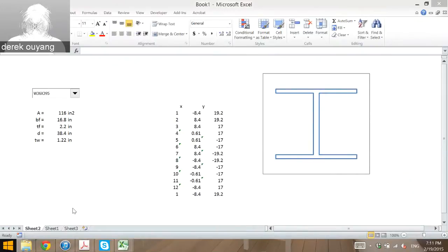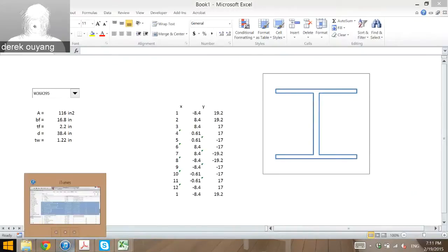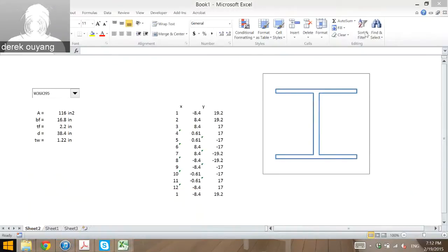That's not part of the assignments, but the thinking there is that if you're in some design process and you had a range, you just wanted to see the available options. This is more likely helpful if you knew like ZX, what you wanted the flexural capacity to be, but you didn't know what depth, because a W8 could do it, but a W12 could do it as well. And so you just wanted to see all those options. So that's just a sorting exercise. But you'll see the sorting exercise might be helpful in a bunch of cases.